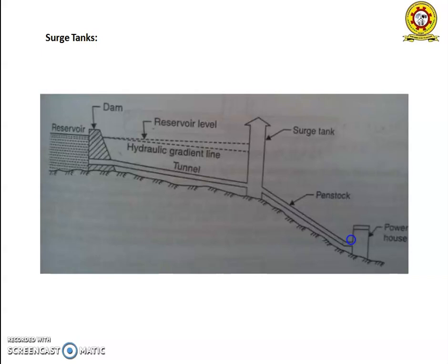In such tanks, an orifice of considerably smaller diameter than the surge tank diameter is installed between the surge tank and the conduit system. When the load on the turbine drops or is rejected, a mass of water enters into the surge tank through the restricted orifice and then builds up quickly a retarding head in the conduit. Such tanks of special design are of use. And differential surge tanks are more efficient than the simple surge tank.